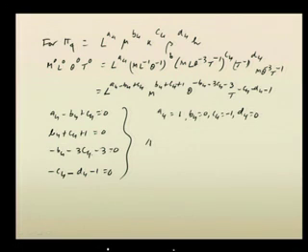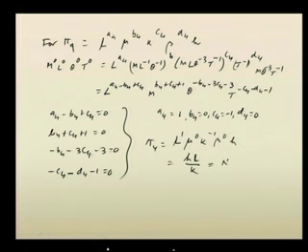Then what we get, pi 4 equals L to the power 1, then mu to the power 0, k to the power minus 1, then beta to the power 0 and h. What is this? This is h L by k. So, this L is small l or capital L, whatever it is. So, h L by k is nothing but it is called Nusselt number.